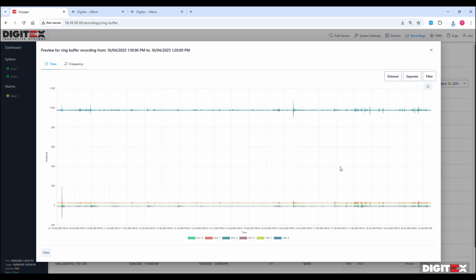That's because we are combining horizontal types of acceleration data together with vertical ones, and they are dispersed in the range from 0 up to almost 1000 centimeters per second squared, which clearly indicates that we have channels here that oscillate around G, which are actually our 2 vertical channels from the 2 accelerometers.